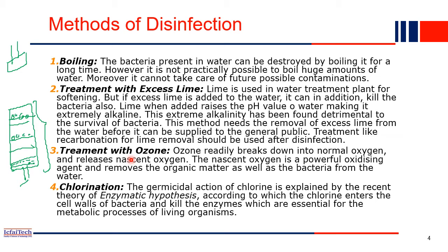That's why nowadays in the electronic water purifier systems which we install in our homes, sometimes they mention ozone treatment in the advertisement. So basically ozone is a very good disinfectant. Again, for large scale use, the cost of cleaning the water with ozone will be very high. For large cities where a larger quantity of water has to be treated, ozone may be expensive.